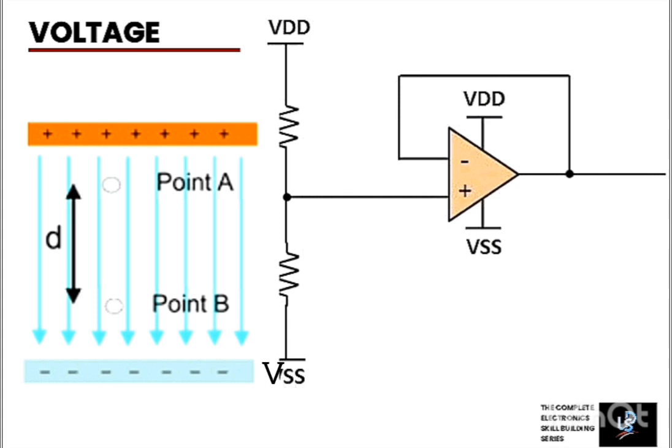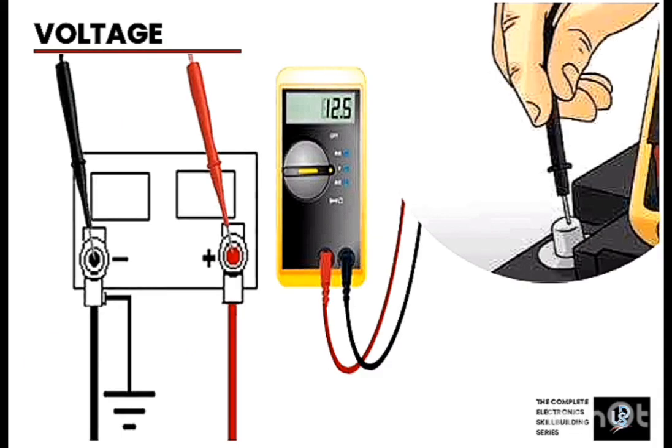A reference point is like a visual guide to help you judge your measurements. For example, it would be impossible to accurately determine the voltage of a battery without taking the measurement from its reference point, that's the negative terminal of the battery.